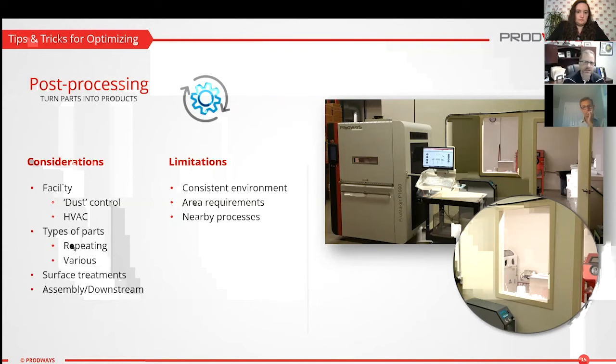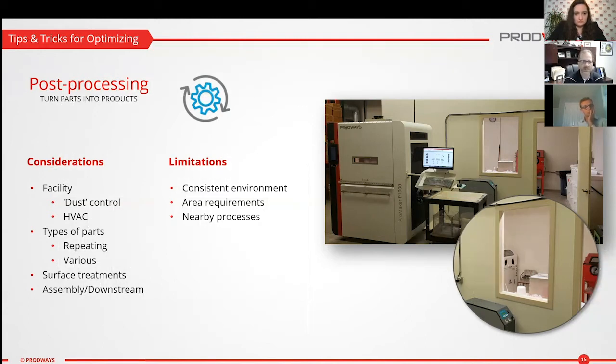You see a separate room there pictured in the right side of the picture. We actually built a separate post-processing room to keep everything contained. Your HVAC system or your air handling system has to be taken into account. Use filters on your air handling system. Don't let the ducts blow air directly on the machine. Things of that nature. Pre-planning can go a long, long way in success.